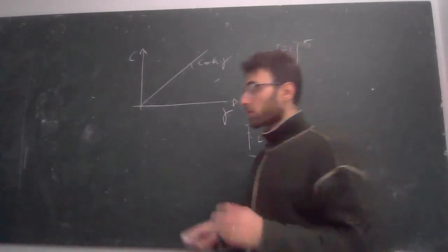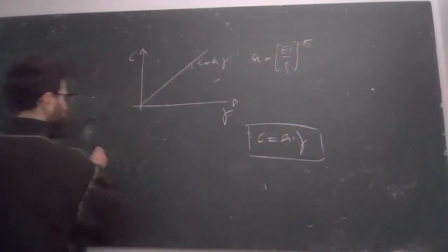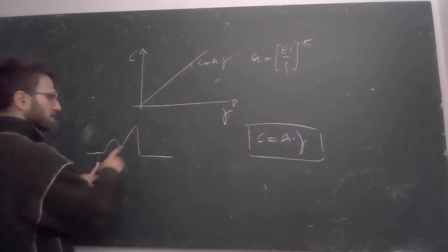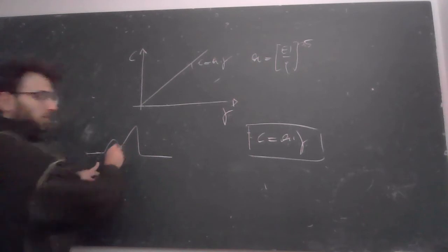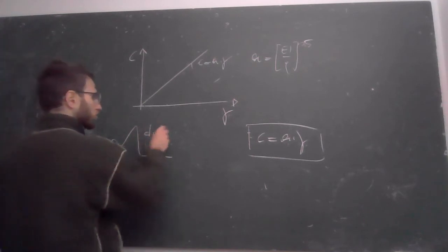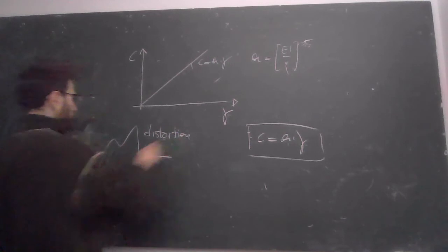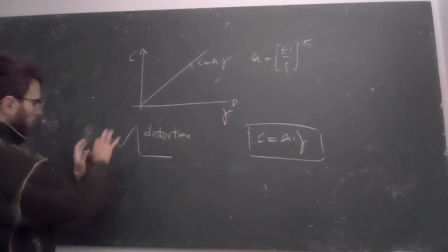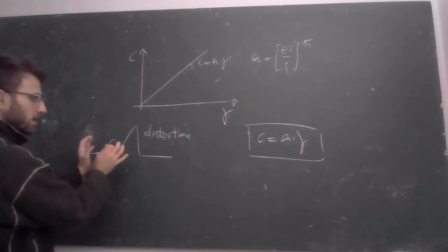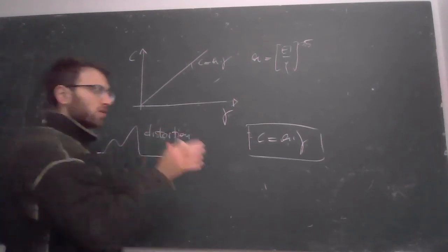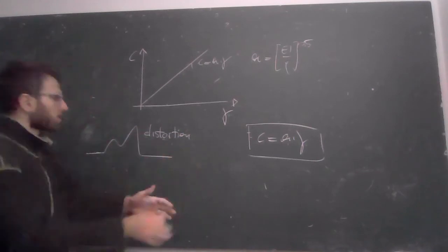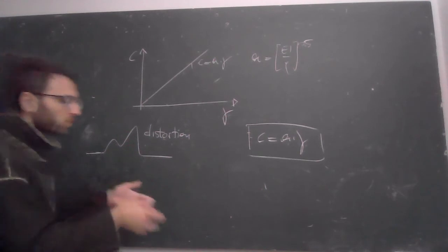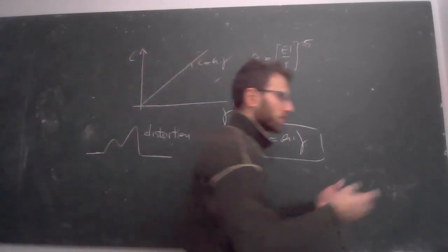This is the dispersion law, which means that if we have a pulse or a perturbation propagating inside the beam, that perturbation will have a distortion. Because the harmonics which compose this peculiar shape, this peculiar perturbation, each one goes with their own velocity. So the shape will change, and we have the dispersion phenomenon.